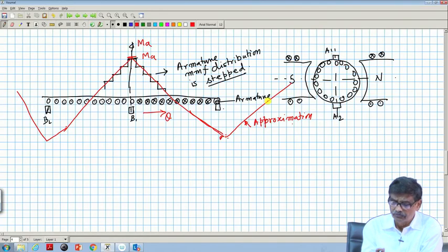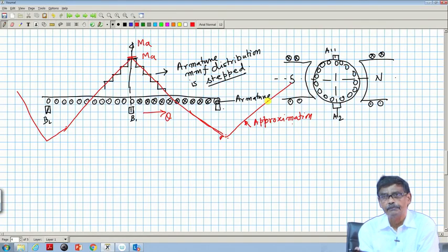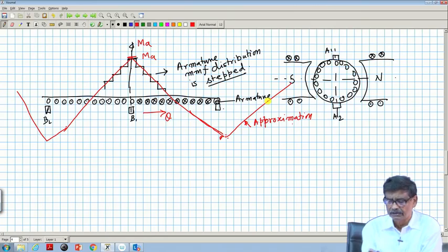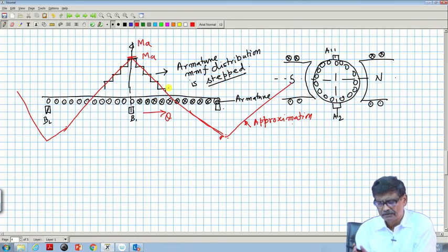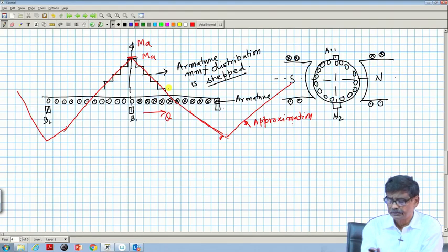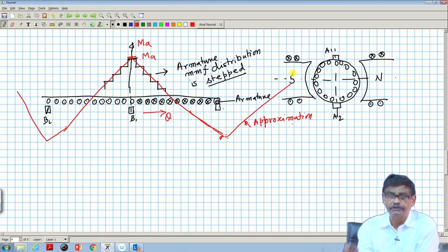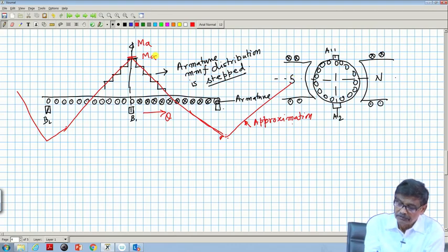And then I know for a single coil how to sketch the MMF distribution, which will be rectangular, plus minus, and we found it out for individual currents. If you sum them up you will get an MMF distribution which will be, strictly speaking, stepped. If a large number of turns and conductors are used, this can be approximated to a triangular waveform like this. The peak value of the armature MMF will occur at the brush positions here.